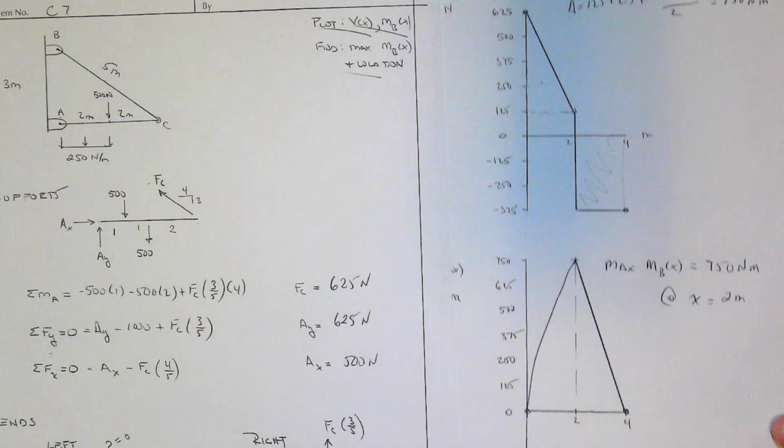All right. So now, the process we'd said is, so we're at 625, we're walking across the beam. So let's walk across the beam up here, and we're going to hit 500 newtons going down linearly over 2 meters. So that would take us, 625 minus 500 would be 125. And so we'll draw that in.